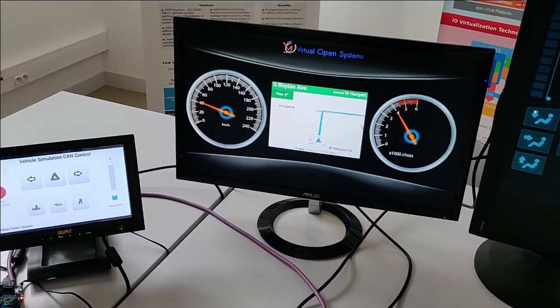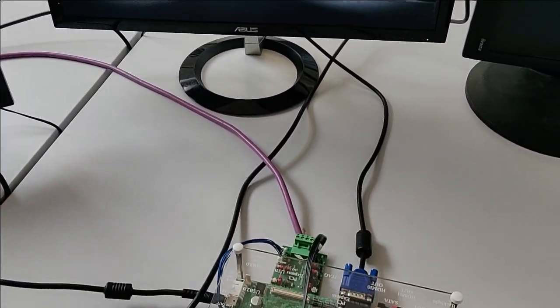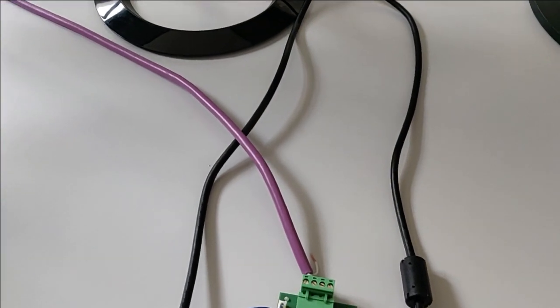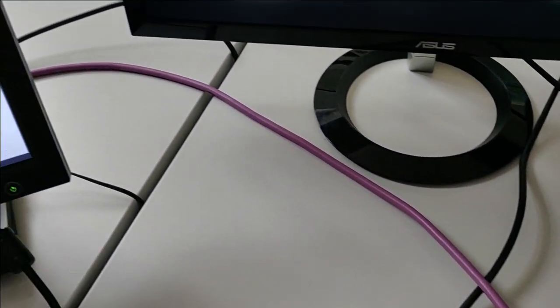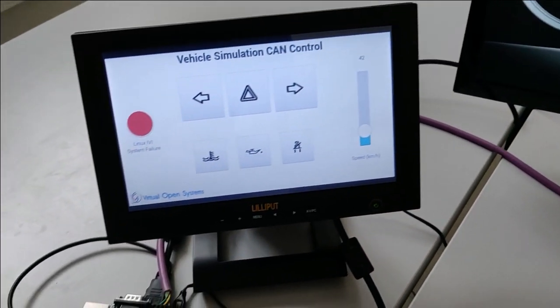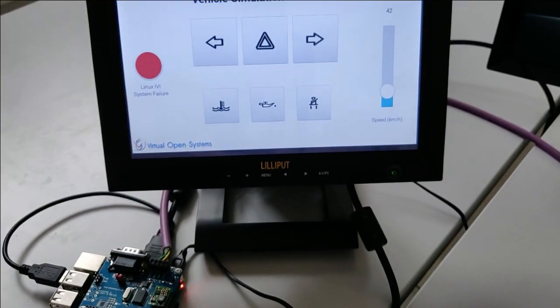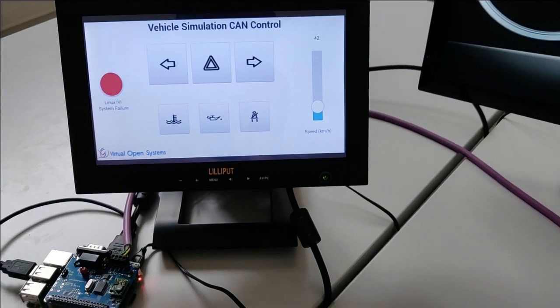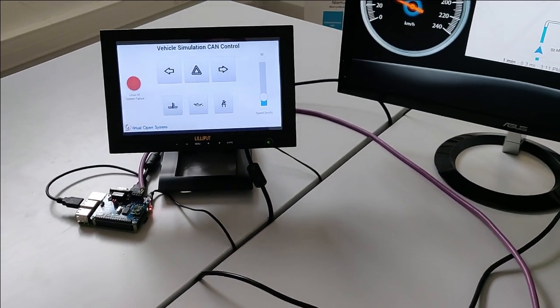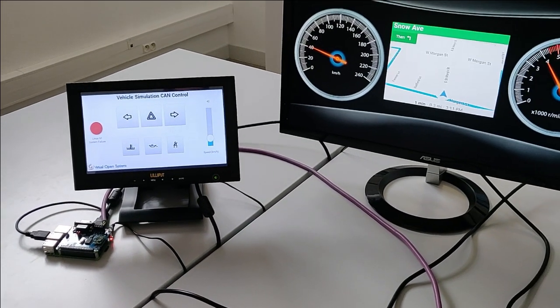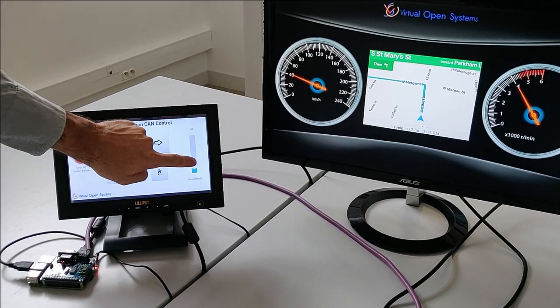As you can see, the CAN bus links the Renesas R-Car H3 Salvatore XS to an external ECU, simulated with a Raspberry Pi 3 board in this demonstrator. A touch panel is connected to the Raspberry Pi 3 platform and allows the generation of CAN messages, like speed instruction, that are transmitted to the R-Car H3 Salvatore XS.